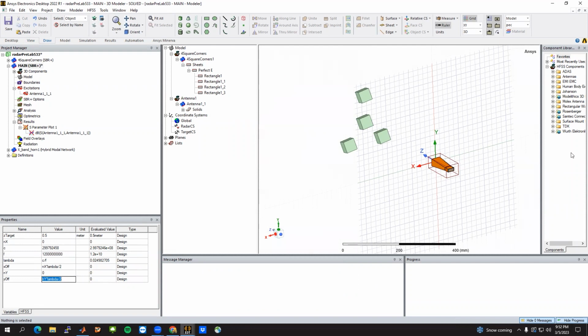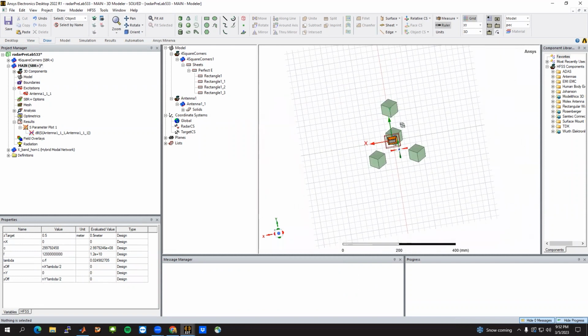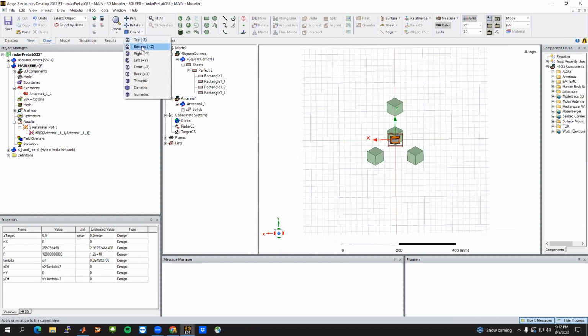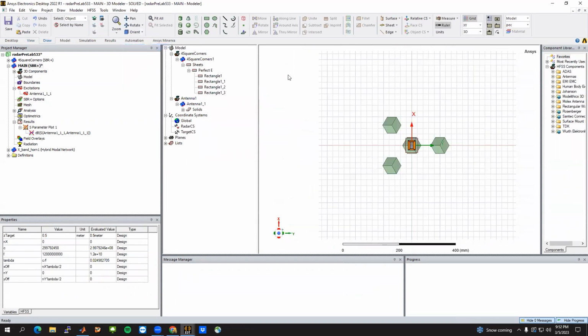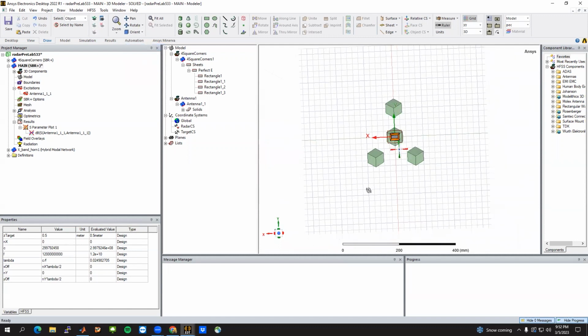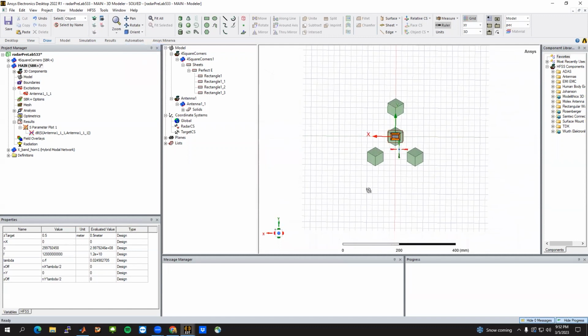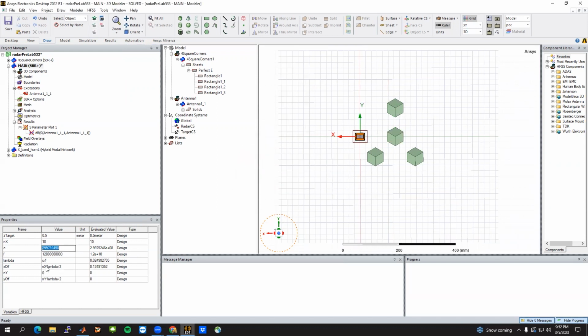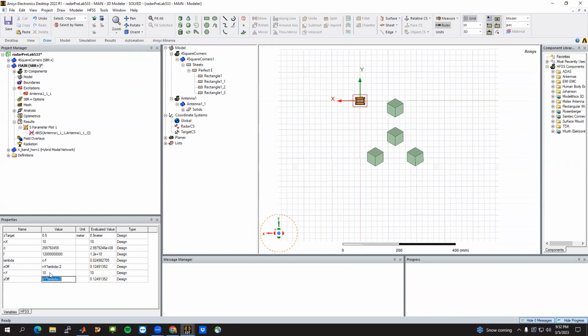And let's say I want to make an aperture that's around 5 lambda by 5 lambda. So you can orient this like this. If I want 5 lambda by 5 lambda, since I've set the step size to be lambda over 2, I need to go from nx equal to 10 to minus 10, right? So I'm just checking now if it covers the whole area, and this looks pretty good.